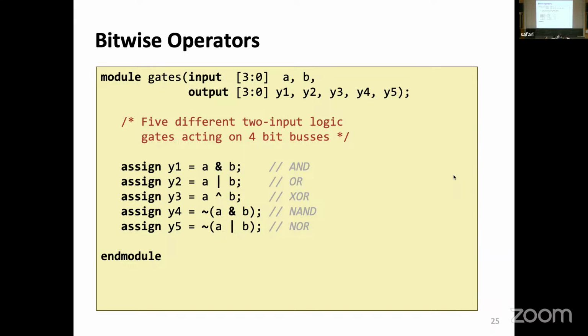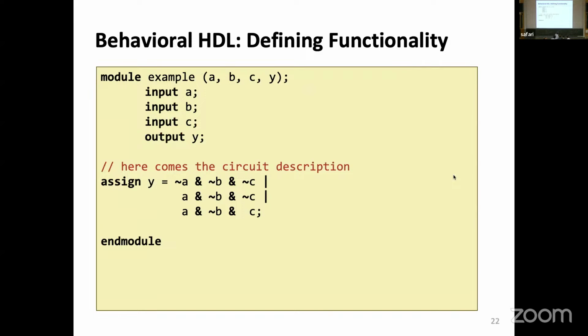So here I'm running a simulation. I took the circuit I had before, and now over time I'm changing the values of A, B, and C, and it calculates what Y will be. What may be confusing here is that I gave A, B, and C through what we call a test bench, which we will see in 2 weeks. In the test bench, I say, wait until 400 nanoseconds and then change A to 1.